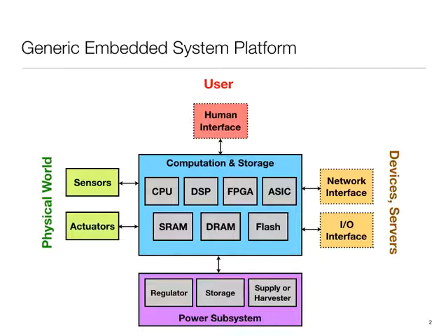And then a very crucial but often forgotten part is the power subsystem, which would have some sort of power supply, battery, energy harvester, like from motion or solar cell or something like that, some sort of energy storage, capacitor, rechargeable battery, and a regulator, which cleans up the voltage before supplying it to the rest of the system. So in a way, all these things are areas of significant investigation on their own, but this is the generic picture.